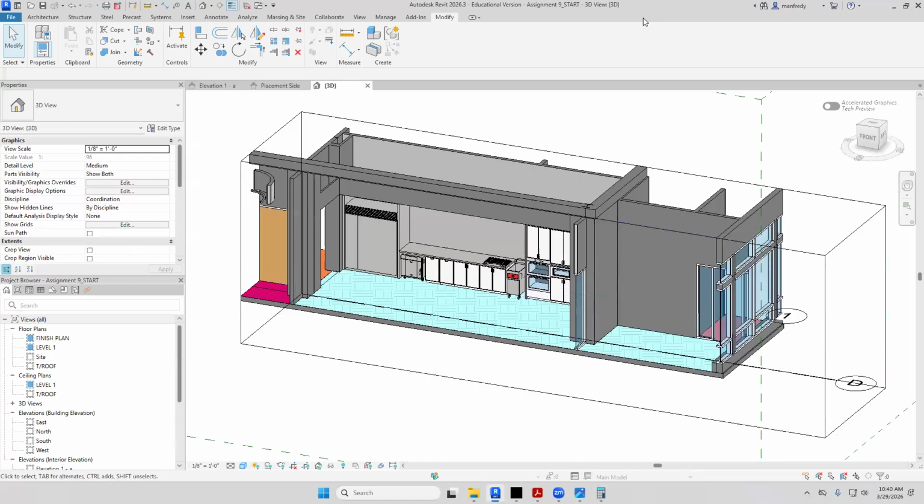Can you copy this to the L drive? Sure. Can I do it here? Yeah. Copy it to the folder. Where would we put it? Okay. No, you have to open it first. Double click on the family. Then go File, Save As, Family.